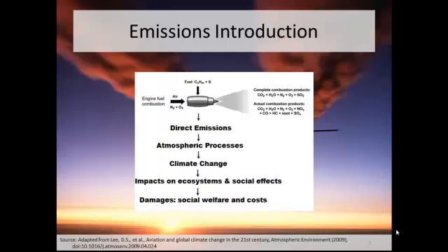CO2 is a product of hydrocarbon combustion. The amount of gases emitted is related to the amount of fuel consumed, which is a function of the engine fuel efficiency and the amount of time the engine is running. Aircraft engine emissions consist of about 70% CO2 and just under 30% H2O, with the remainder of pollutants making up less than 1% of the total.